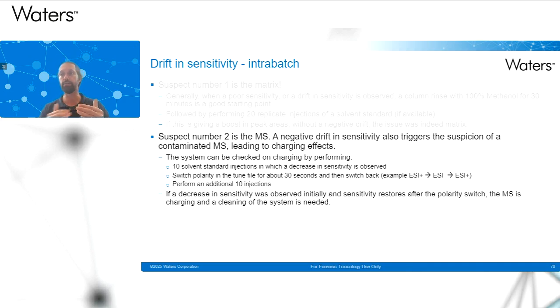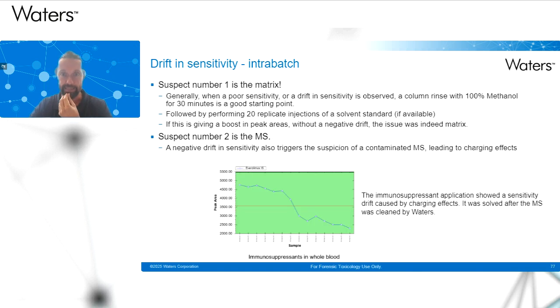If you then see that the sensitivity is back up again and it starts to decrease again, then for sure your system is showing charging effects. And then it's time to call Waters, indeed, to have your system cleaned. This is what was the case for the immunosuppressants in whole blood, and that was solved after a cleaning intervention by Waters.